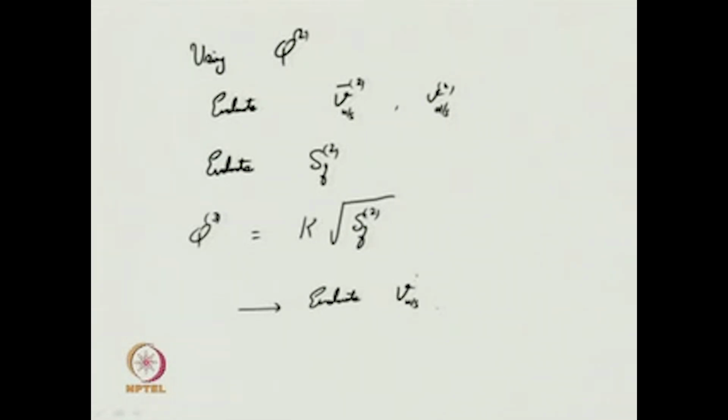Once you get Q3, go back again and check it. We are going back again because we find that Q2 and Q3 are not the same. Similarly, Q in the first approximation and Q in the second approximation are not the same. So, we keep going back like this till two consecutive approximations give you the same discharge.